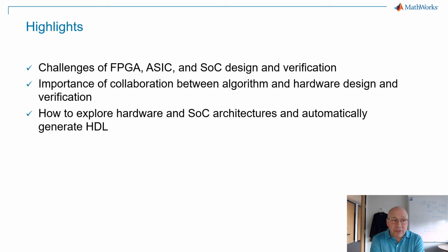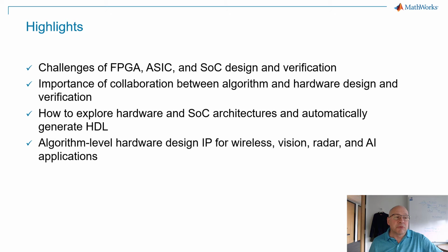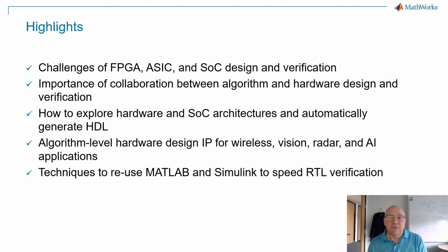We'll use an example design to show how some of the design tools we have can help in exploring hardware and SoC architectures using simulation, followed up with automatic code generation for VHDL and Verilog. And we'll quickly look at how high-level IP fits in and how integration with popular workflows can help you design for a variety of applications. And finally, since design is pretty worthless unless it's been verified, we'll cover how you can reuse the work you've done in MATLAB and Simulink to build your test environment.